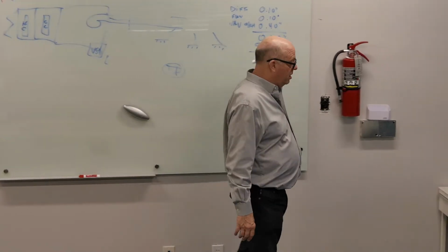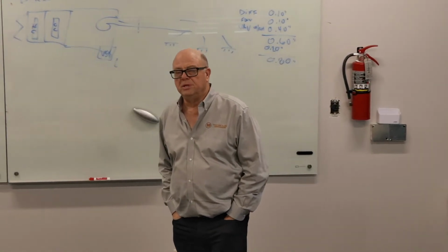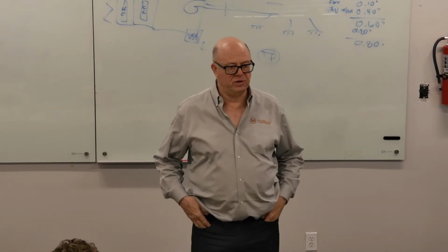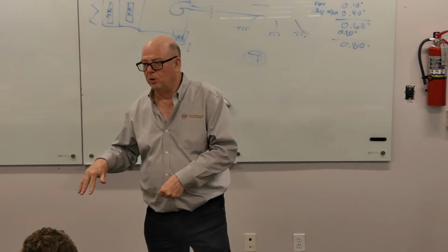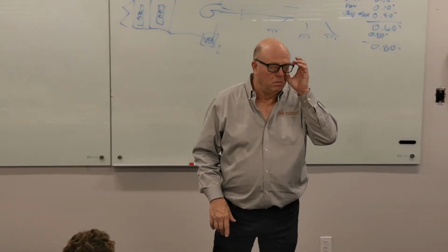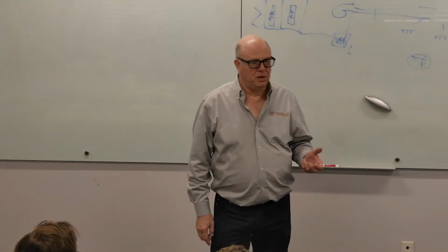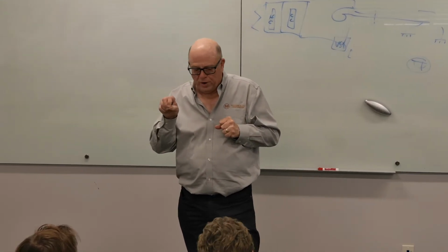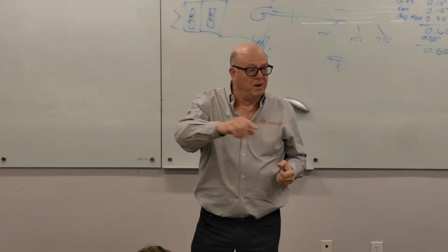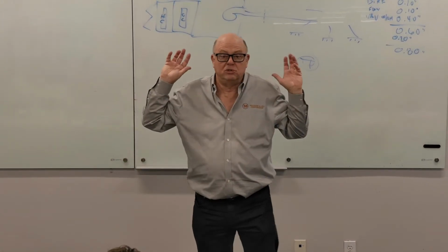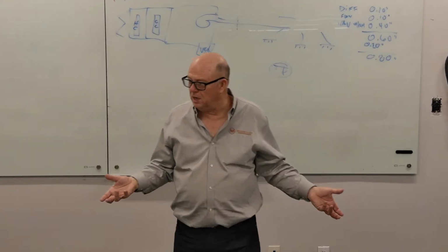Okay, we didn't talk about chilled water reset much. Our ability to do chilled water and hot water reset, in other words, adjust the temperature that the chiller is making or adjust the temperature that the boiler is maintaining in the loop, our ability to do that is dramatically improved with digital controls. Because now, instead of looking at 1 point or 2 points and making a decision, if we choose to, we probably have all that information available globally. It's just a function of how many sensors we got, right? You've got all those room sensors, and you probably have some sensors in the piping and so forth.